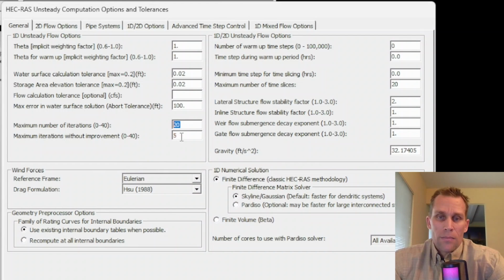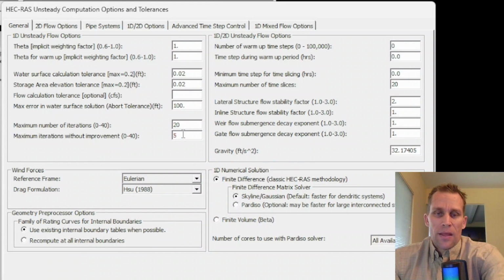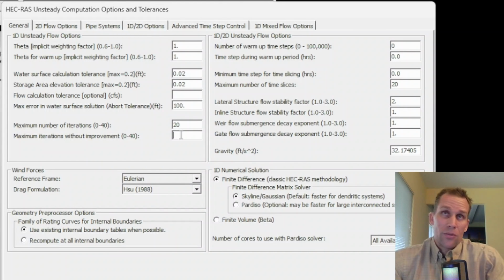The reason being, maybe computations take a long time and all hope is lost of any improvement if you can go this 5, or whatever maximum number of iterations, without any improvement. You might as well just quit. And then the final result is not the final value, but rather the best value, so HEC-RAS will go back to the best previous iteration's value and return those numbers.